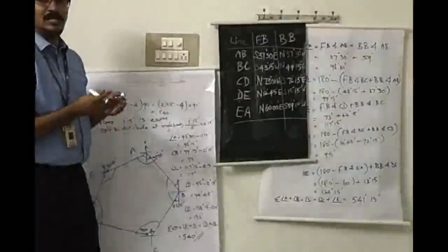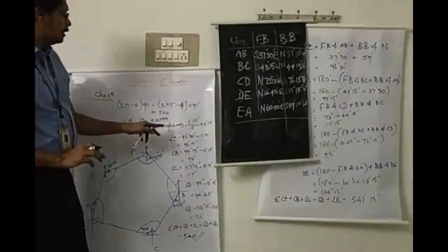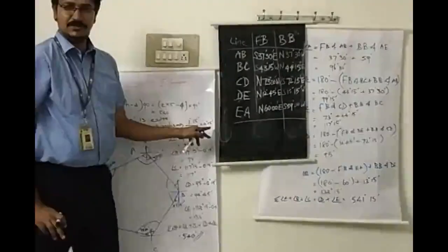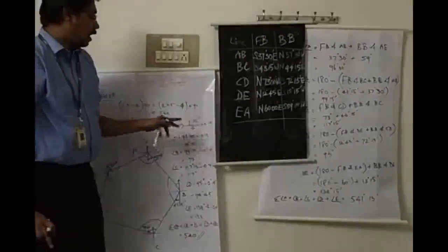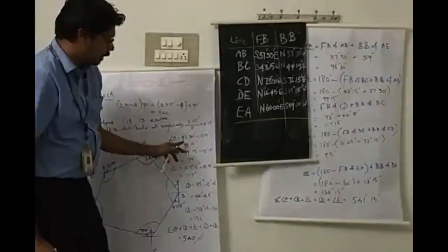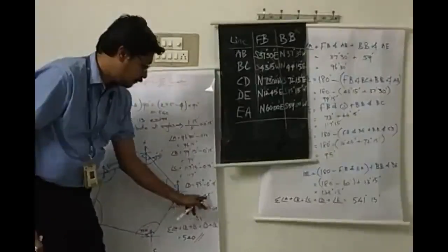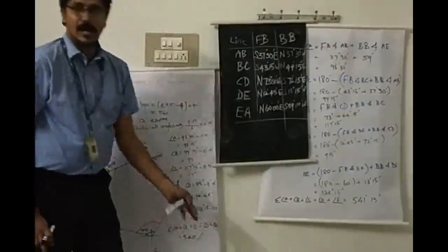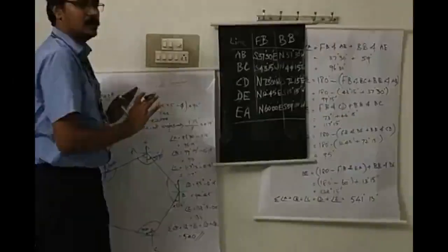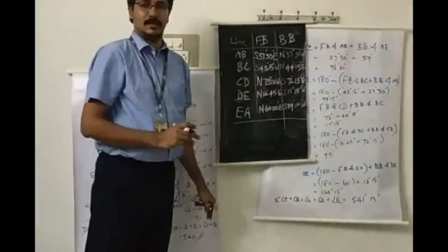So this has to be deducted from all the included angles. How can we deduct? Split the angle into equal 5 parts. 1 degree 15 minutes divided by 5, you will get just 15 minutes. Subtract 15 minutes from all the included angles. So you will have 96 degree 30 minutes, 96 15, 99, 117, 94 45, 133. If you sum it all, again you will get 540 degree. Right? So this is the way of summing. But if you want to correct the angle also, that we will continue in the next video. Right? Thank you.